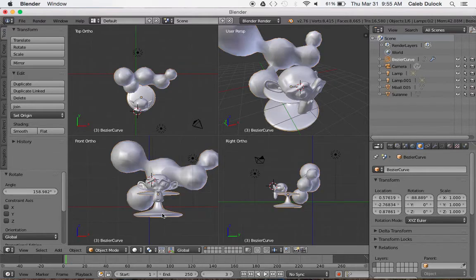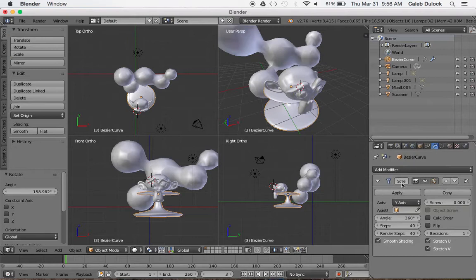Now there are other things in my scene that are not correctly converted into other objects. This object that I've selected right now is actually made from a curve and a modifier, as you notice in my outliner up here in the upper right. It is not recognized as a mesh object yet. So that's something that I also need to convert into a flattened object. So I'm going to apply the modifier by going to the property panel for that object first.